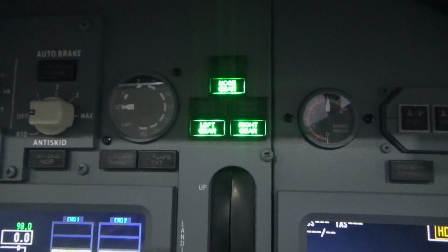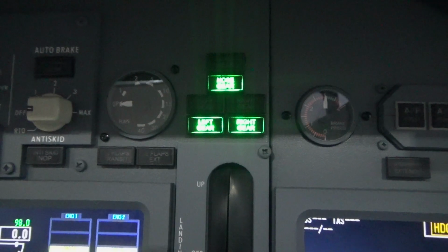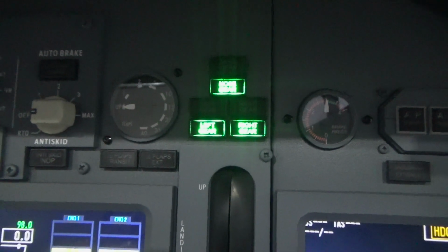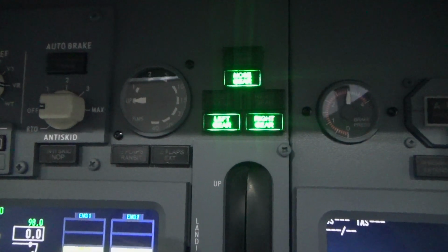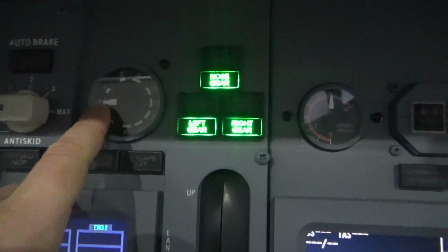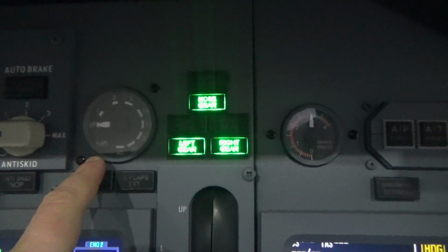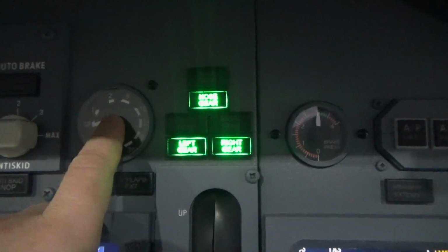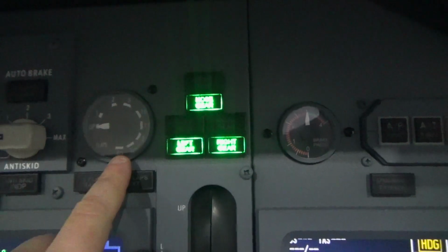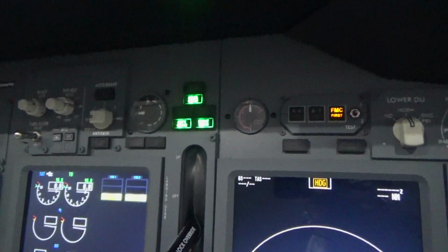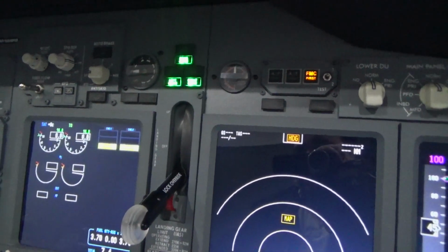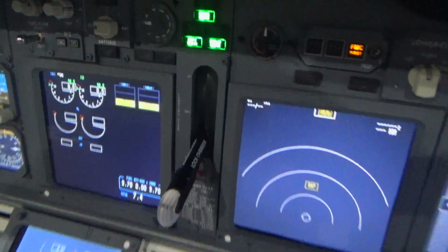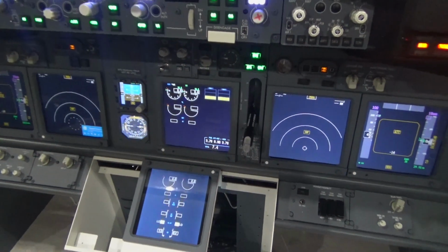You go into ProSim config drivers and find the drivers for the flap gauges, and there is a slider. For position 0, you move the slider until this one shows position up. For position 1, you move the slider until this one shows position 1, and then 2 and 3 and so forth. And the same for the brake pressure. Everything is quite easy, intuitive, very user friendly. Once everything is done, you can obviously test. So let's start up the simulator and see how everything looks.